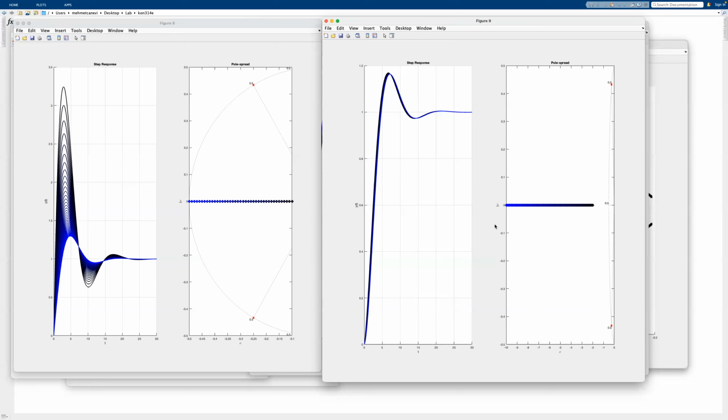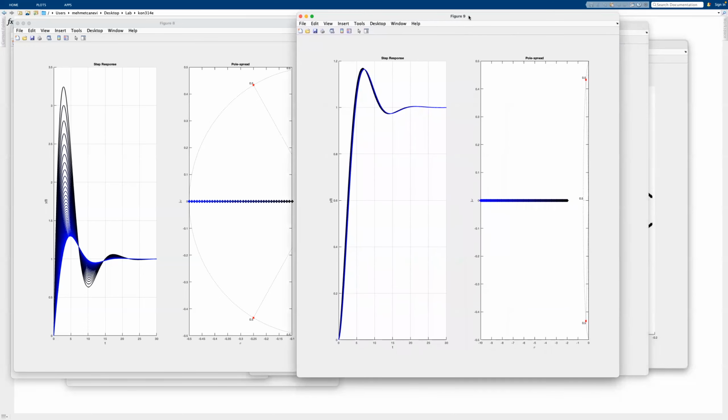This was basically an explanation for last week on how we designed the P-type controller, because all we knew was the second order part of the system, but we hoped for the best and we ended up with a dominant pole assignment result that was usable. Of course, it was picked carefully, so that's the reason why. But yeah.